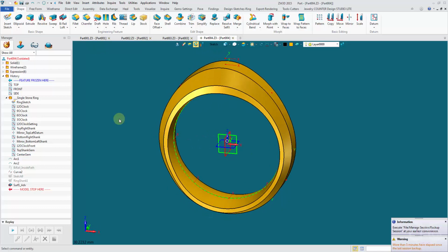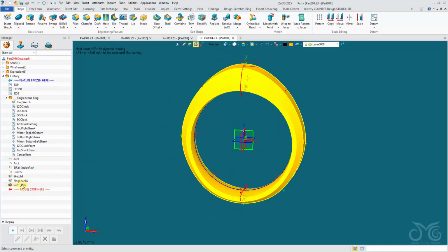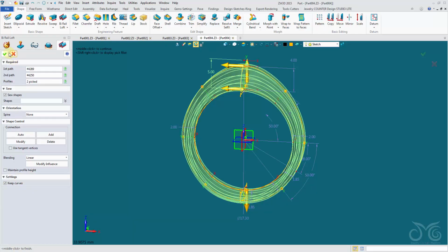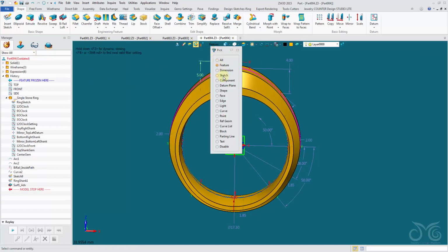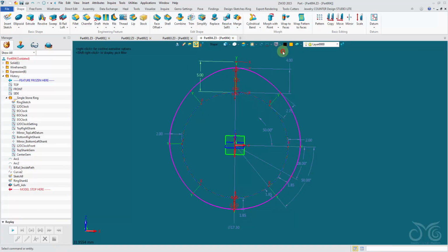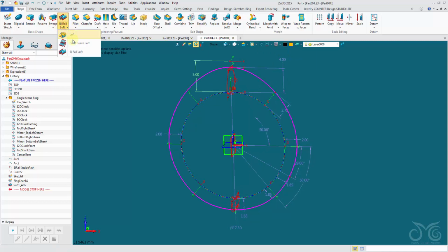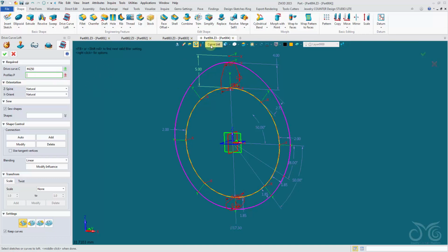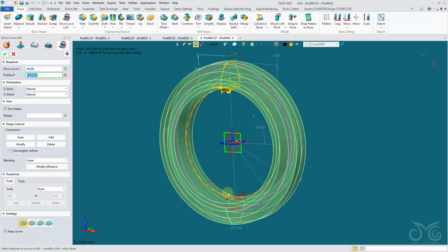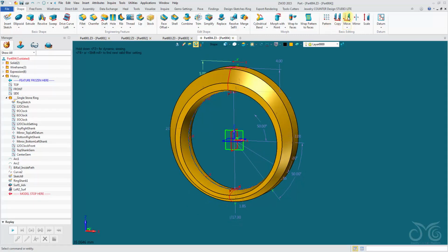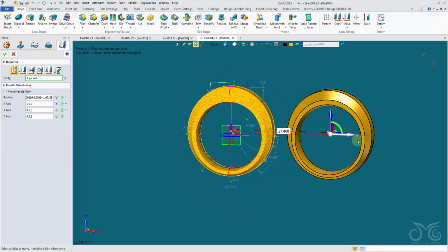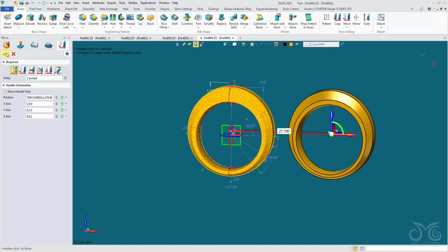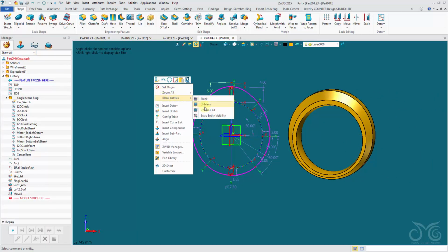of the ring shank. How about if I compare it? Let me just keep the curves. We need to blank out this shape. And this time we'll just do a drive curve loft with our inner curve only. Profiles, sketches. Let's move it. Right click, blank entities, unblank all.